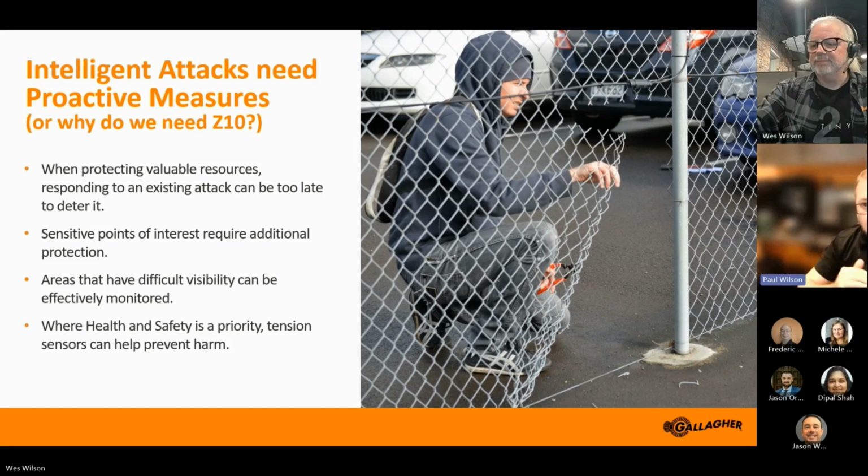If you're putting a wire on every Z10, right? And then you would group that by the controller that's managing that, or the fence controller that's managing that fence zone, which would in turn be managed by a specific 6,000, 7,000 controller. So that's how it would actually logically break down. You wouldn't necessarily go out there and say, hey, I want to chain together 75 Z10 sensors all off this thing, because you lose some of the fidelity of the detection range on that, right? You don't know where whereabouts that sensor is and why did it trip? So you want to keep that in mind when you're actually designing these.